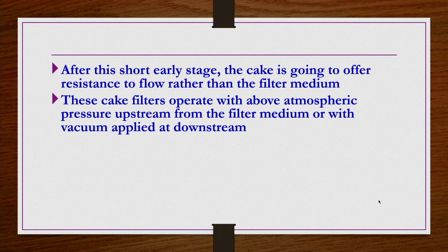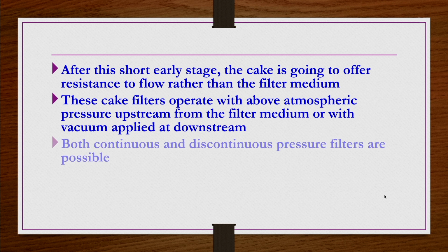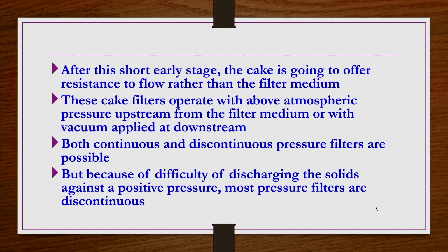These cake filters operate with above atmospheric pressure upstream from the filter medium or with vacuum applied downstream, and both continuous and discontinuous pressure filters are possible in general. But because of the difficulty of discharging the solids against a positive pressure, most pressure filters are discontinuous.